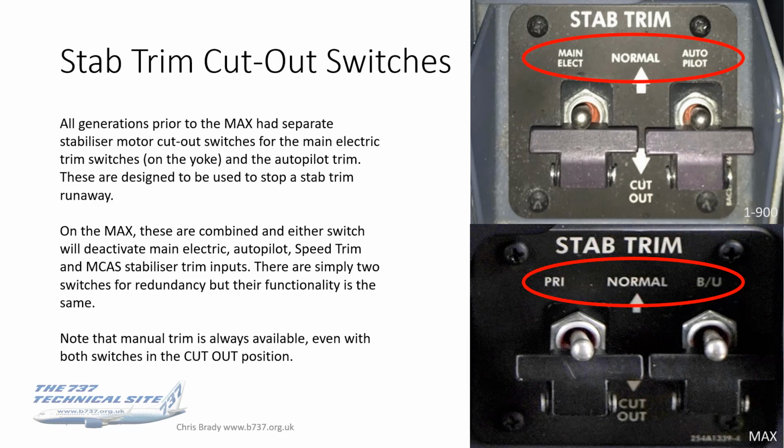Just a reminder that manual stab trim is always available, even if both of these switches are in the cutout position. Again, I'm sure you all know that, but it never hurts just to be reminded of these things. Manual stab trim will override anything. It's always available as long as there's a cable linkage to the back.